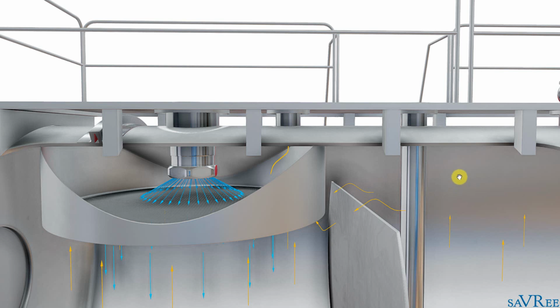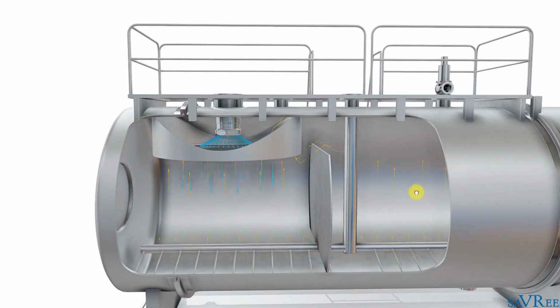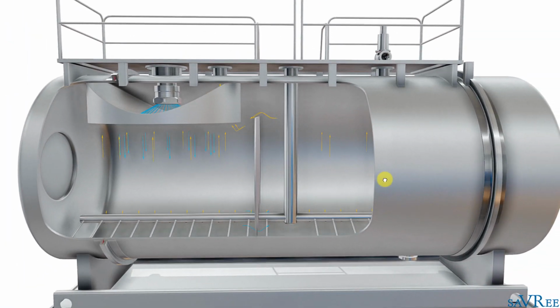By removing the non-condensable gases, specifically CO2, carbon dioxide, and O2, oxygen, we're going to reduce the risk of corrosion. CO2 makes the water more acidic, and oxygen can lead to oxygen pitting and general corrosion. We may also add chemicals such as hydrazine to the deaerator, which is going to further reduce the amount of oxygen dissolved in the boiler feedwater.